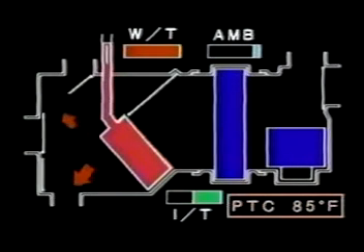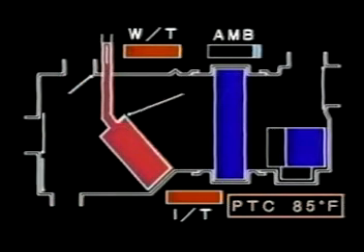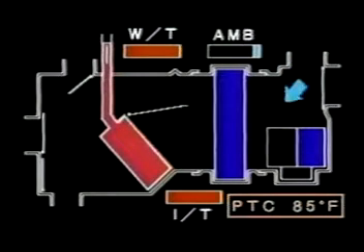As the in-vehicle temperature approaches the set temperature, the air volume gradually decreases and the air mix door gradually closes. Eventually, the in-vehicle temperature reaches the set temperature, the air volume will be decreased, and the air mix door will close to the objective position where the set temperature can be controlled.